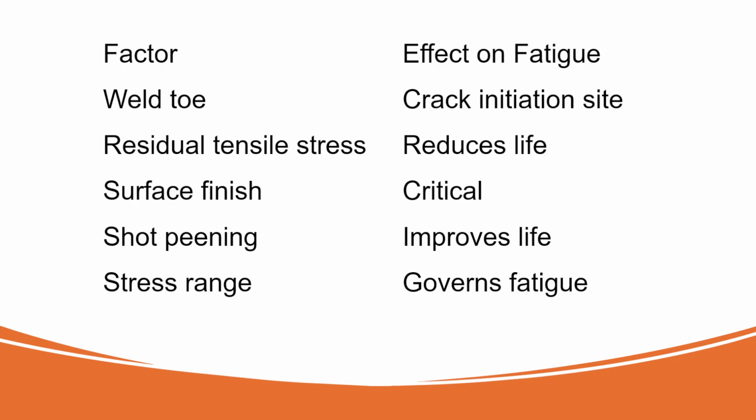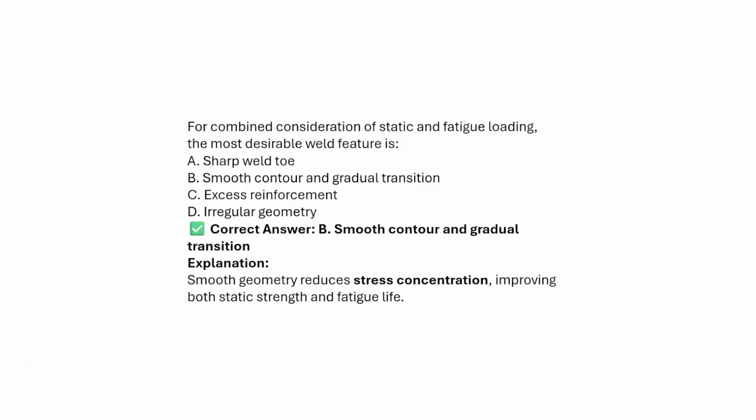Factors: weld toe is the effect on the fatigue crack initiation site. Residual tensile stresses reduce the life. Surface finish is critical. Shot peening improves the fatigue resistance life. Stress range governs the fatigue. Okay.